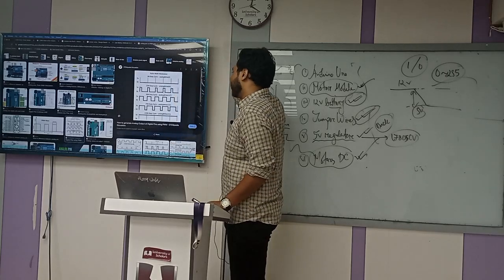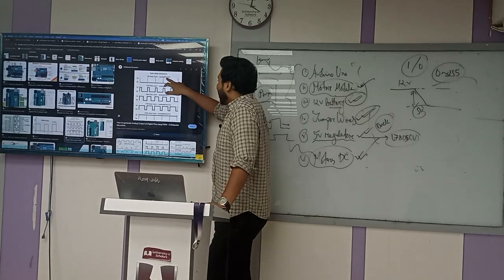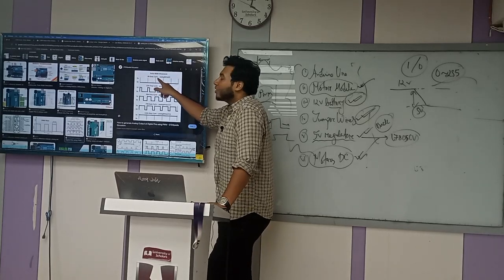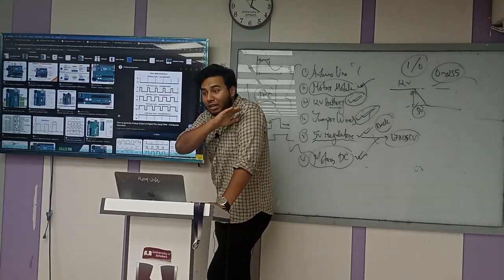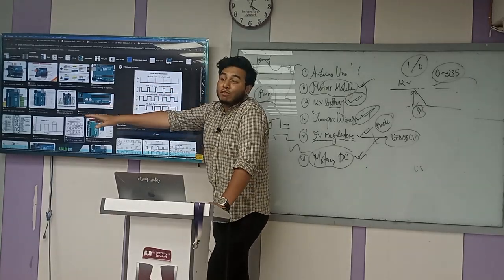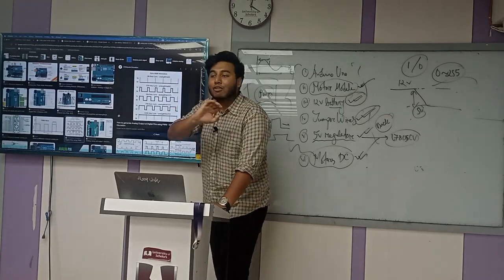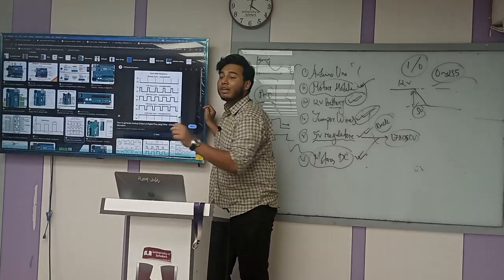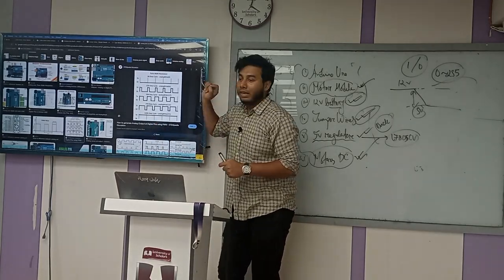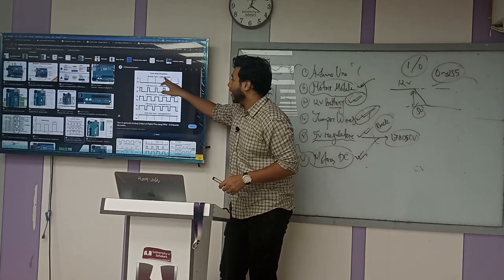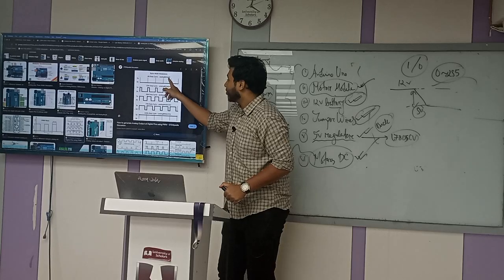Yes. Okay. So if you write analog 0 in the code, you will get a 0% duty cycle. So it will act like a 0 voltage, same as digital write 0. You will not get any difference between writing analog 0 or digital 0. The difference is in the coding. This code part actually opens up that pin and closes that pin by using 0.